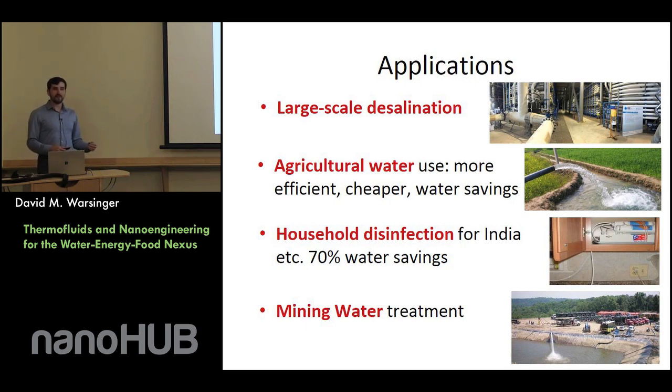In more developing places, it can often be more than 2/3 of their water being lost. So what they do to conserve water is they shut off their water systems at night and during low demand periods. That saves lots of water, but if you have a depressurized pipe, you shut off the pressure, other water from outside can infiltrate, right?